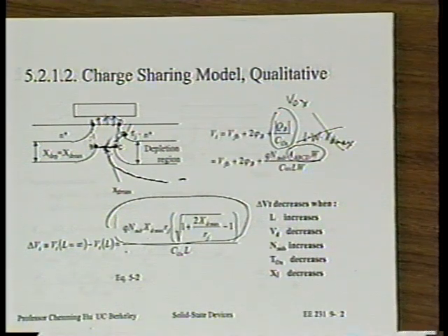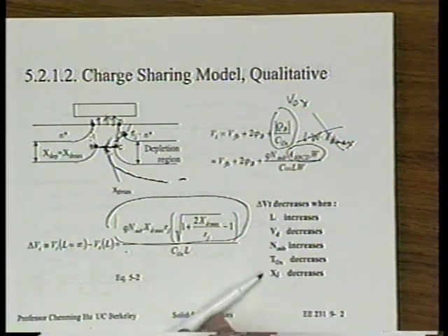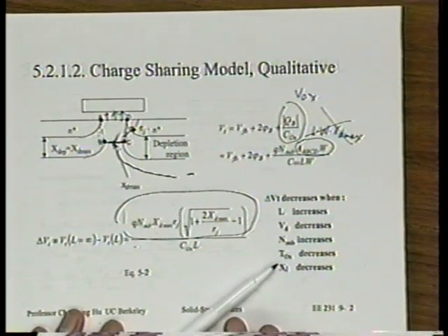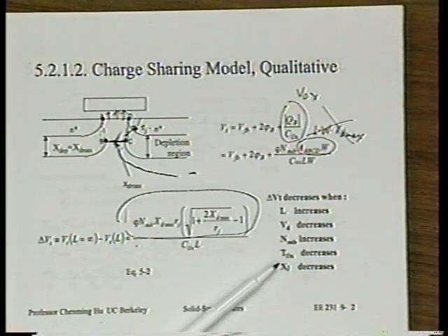All right? Maybe you say this is cheating. Turns out it's not cheating. Let me tell you, of all the possible solutions to minimize short channel effect, using thinner oxide is the best one, the most practical one, because we want thin oxide anyway. It doesn't hurt anything. We always want to use the thinnest oxide. Anytime you're not using thinner oxide, you're getting worse short channel effect than you need to. Doing other things is actually harder. So this turns out to be the best thing to do. When you want to improve short channel effect, make sure you're using the thinnest oxide. Okay?